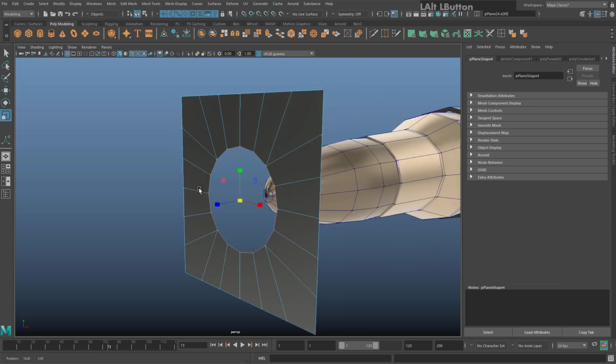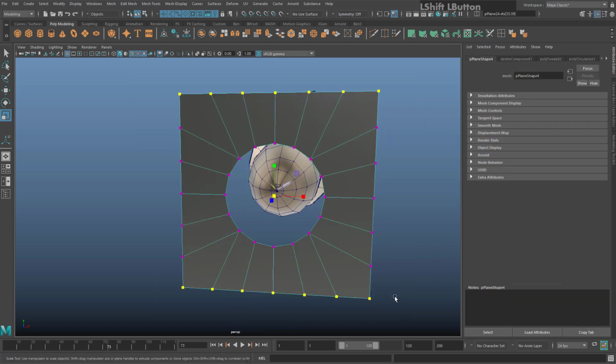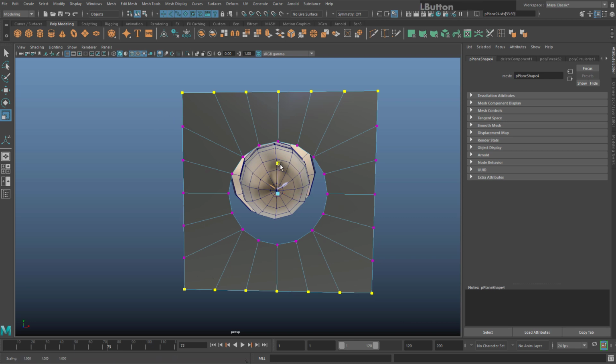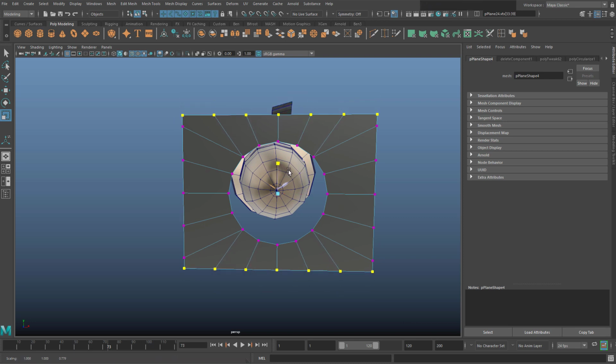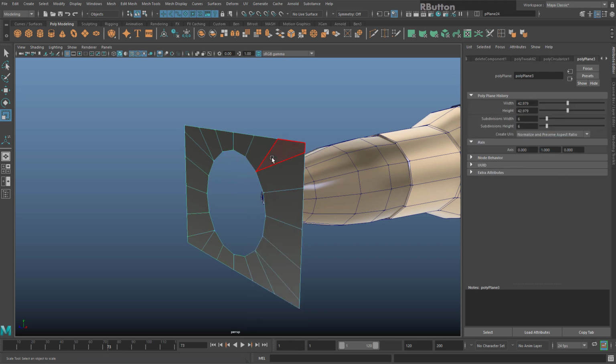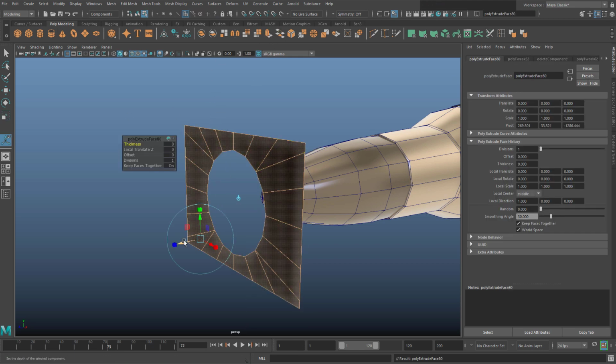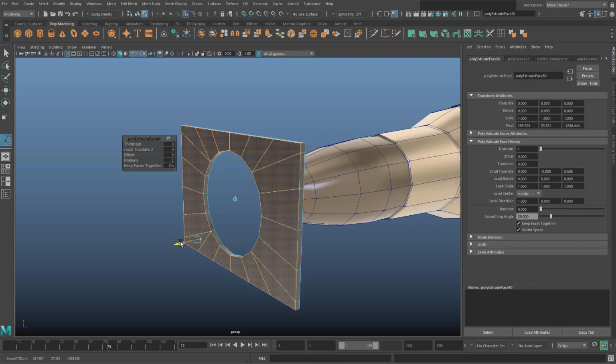This case seems to be rectangular. I'm going to shift select the top vertices, shift select the bottom ones, make sure you don't get any on the sides, and just flatten that out a bit like this. If you need to select these guys as well, you can, and just resize that down to about there. Great. Go to face mode, double click on all the faces, extrude with the extrude button. Don't hold shift, it can cause glitches on this type of thing, and put that to there like that.